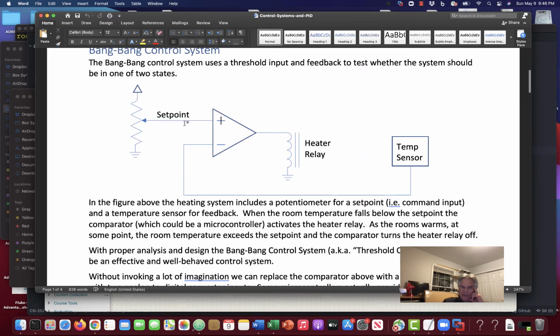If you think about something like this, it could be done with an analog comparator, and has been done that way. With an analog comparator, there are circuits with some feedback resistors where you can even create some hysteresis if you want. But if not, you can build one that has one single threshold if you like. And as you can imagine, this is not hard to do with a microcontroller either.